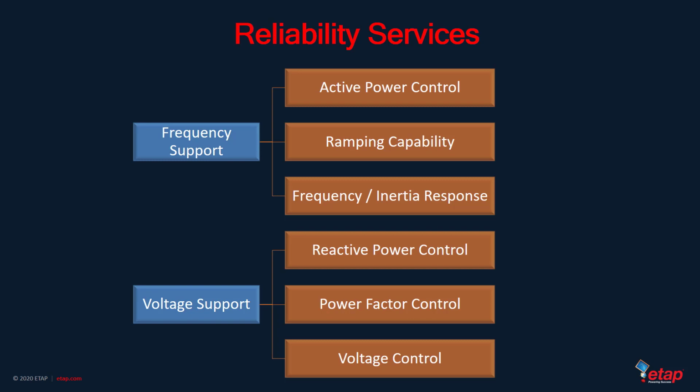Let's talk a little bit about voltage support. The system voltage is critical for reliable power transmission. Therefore, a steady fixed line voltage is critical for the function of most electronic equipment. For these reasons, system operators and generators play an important role in regulating and supporting voltage. Line voltage is primarily supported through using reactive power. Throughout the day, line voltage can differ depending on the system state and loading. It's not an uncommon requirement for a plant to be capacitive during some points of the day and inductive during other periods. This dynamic reactive power control is a function that PV inverters can excel at.